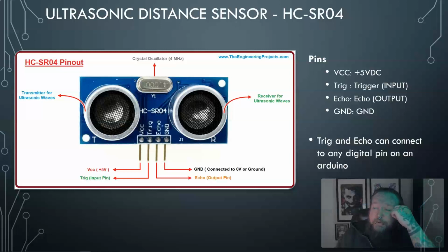And you can see from this one, we've got the VCC, the voltage, and it's saying plus 5 volts. So we're good with the Arduino. That's providing enough. Anything higher, we'd have issues. But we know this should be fine. We have ground, so 0 volts, we're fine. You have the two parts, the transmitter and the actual receiver of the ultrasonic wave.